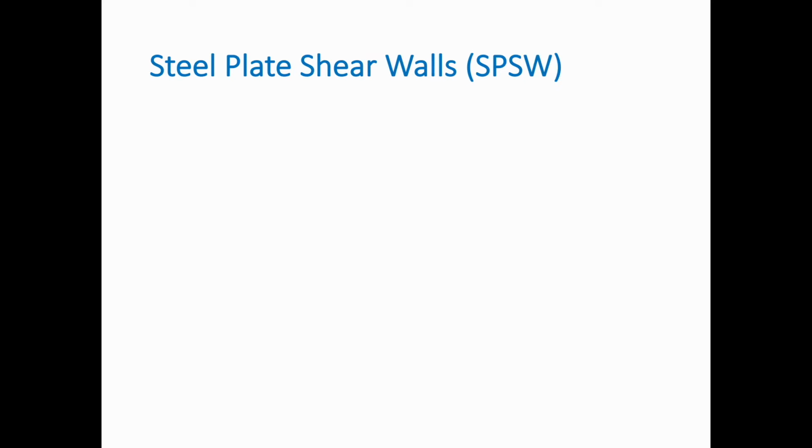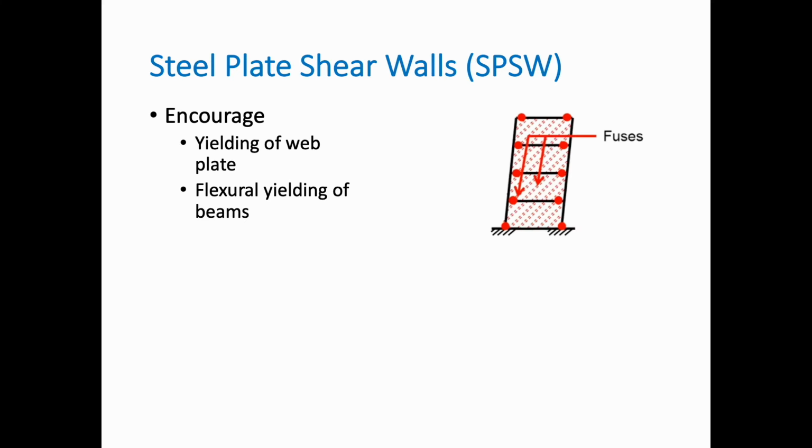Next is a system that we haven't seen used too much, especially in Europe, but it has been used in other countries, and this is the steel plate shear walls. There is more and more research, experimental and computational, coming up with this. I must say that I'm also working quite a lot on steel plate shear walls, and that's an interesting system, in fact.